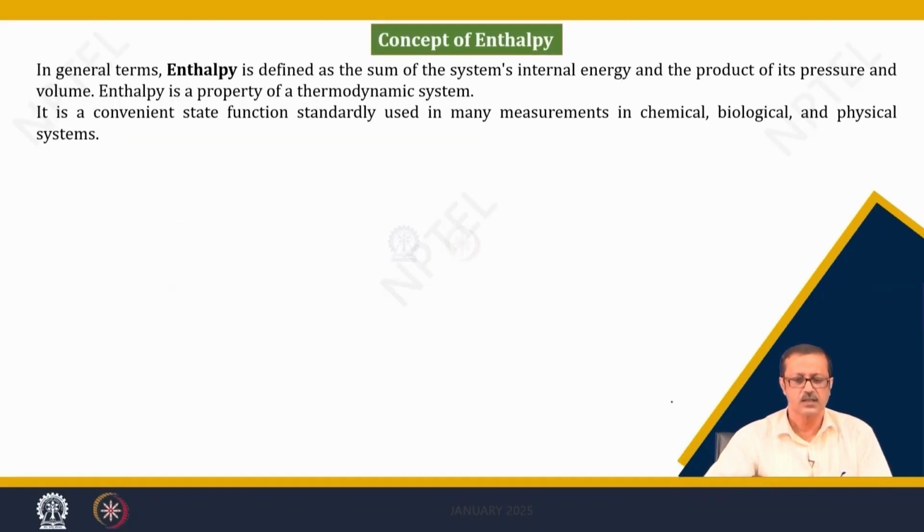Now the enthalpy. Enthalpy is a concept defined as the internal energy of any such product; particularly we will say here for the air. Air has a sensible heat component because it has some heat, it may be at 15 degrees or 20 degrees, so it contains some sensible energy. It also has some amount of moisture, and the moisture has a latent heat component.